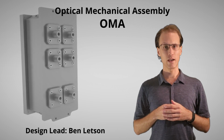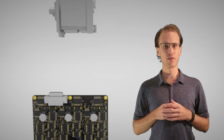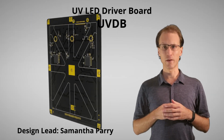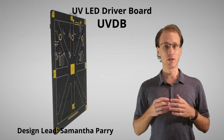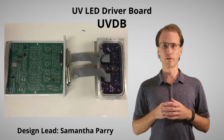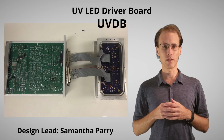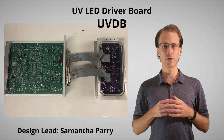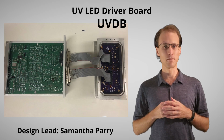Okay, so we have a housing for the LEDs, but what about a way to drive them? Allow me to introduce the UV LED driver board, or UVDB. You can drive 3 LEDs independently, each with their own peak currents formed into the required pulses. It monitors the photodetector and temperature probes inside the OMA, the number of pulses that it is producing, and the average voltages and currents that it is generating.